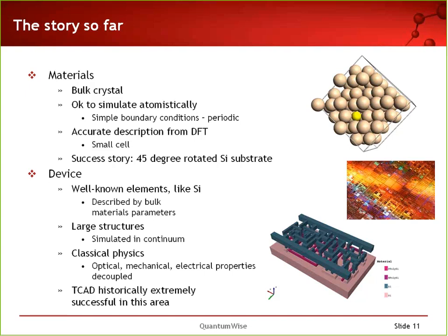On the other hand, the devices are very elaborately simulated. There's a whole hierarchy of EDA tools, and at the lower bottom we have TCAD, and then you have chip design, and so on. And modeling has been extremely successful in this area, but you are really simulating continuum processes, like I mentioned. The current is described by Ohm's law. You can include various types of physical effects, almost like a finite element type simulation. And you do this really in continuum.